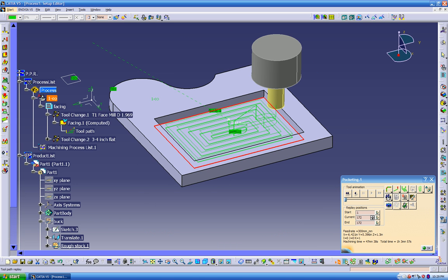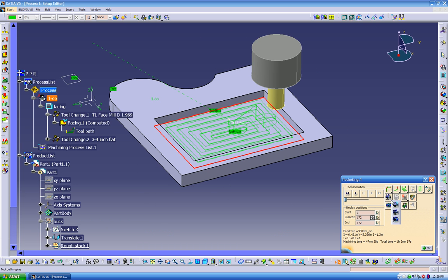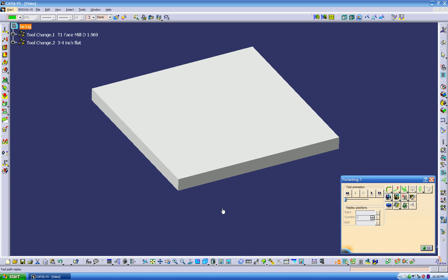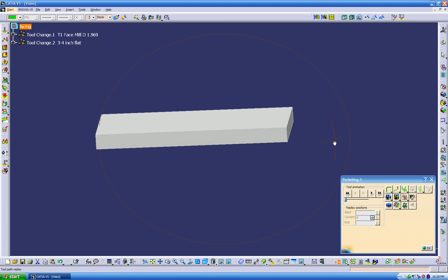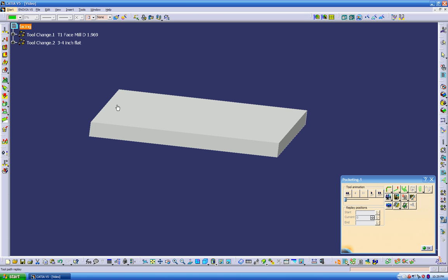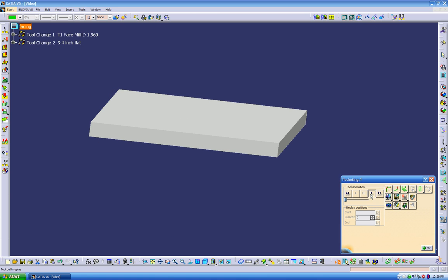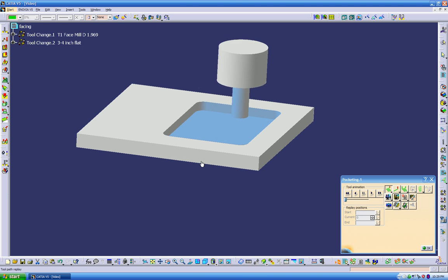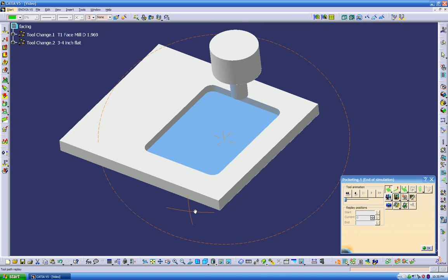Let's do right now a quick replay. And now we can actually go to view the video from the last saved result. And if we click play, this is not the finish, this is not the raw material, this is already using the previous operation. And we can do a play. We can turn this option back on. Now if we do a play, we can see our pocket running. See, we have the finishing over there.